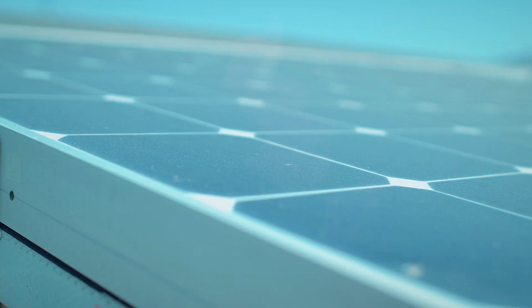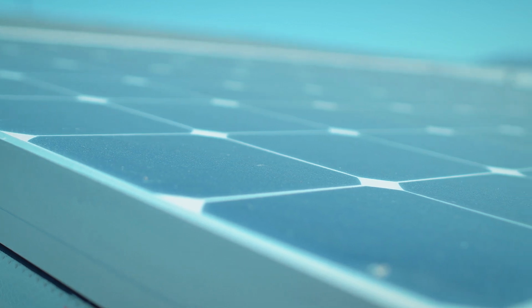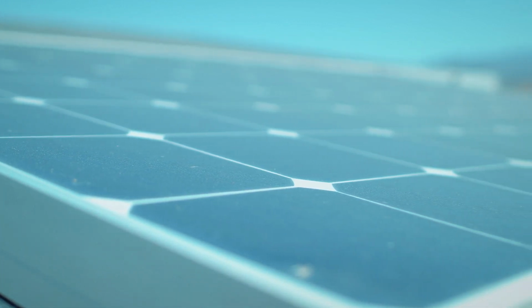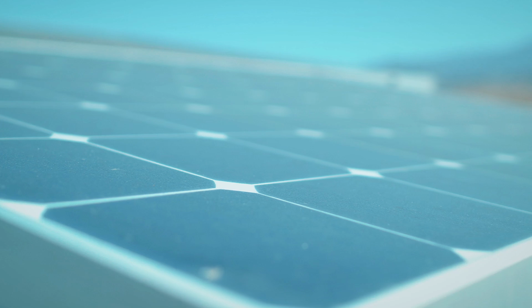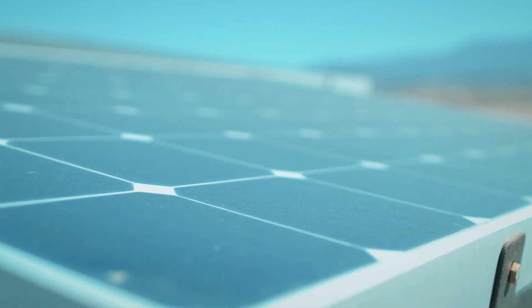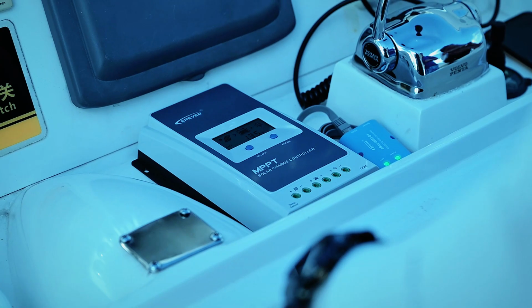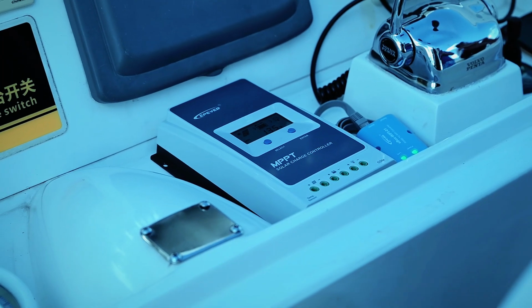to operate. Undoubtedly, increasing our budget would buy more solar panels. Paralleling solar panels isn't necessarily a bad option either. If we build our solar system in series, then you will also need an MPPT charge controller to make the system work. And MPPT charge controllers are generally more expensive and may be more of a budget concern for a small low